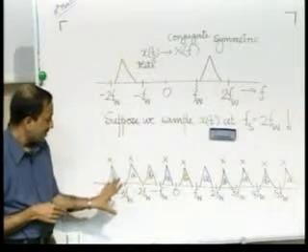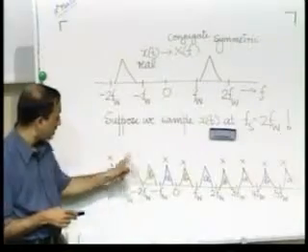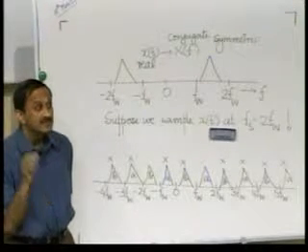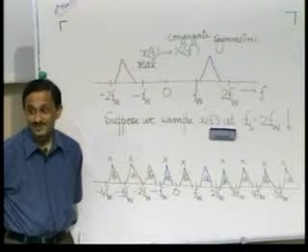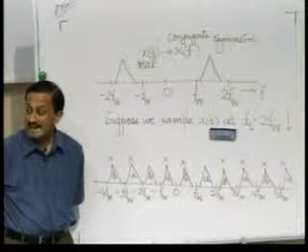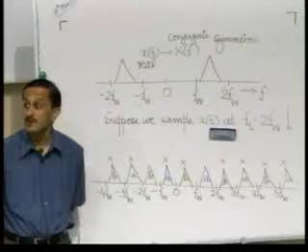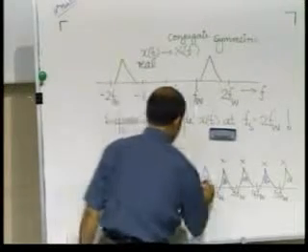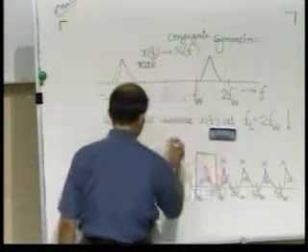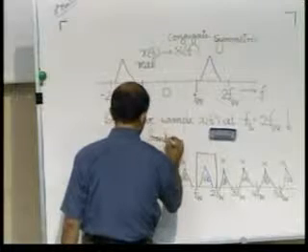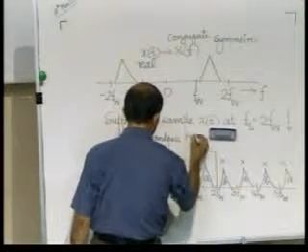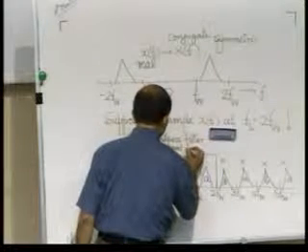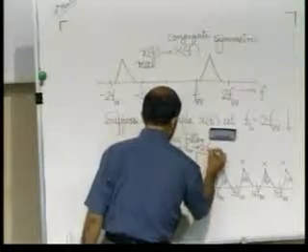Now you see, as a consequence of aliasing, we have created all the crossed spectra that I have shown. But none of those cross spectra interfere with the original spectrum. So, can we reconstruct the original spectrum? Certainly, but by what mechanism? By using a band pass filter instead of a low pass filter. So, suppose I put a band pass filter with a pass band from Fw to 2 Fw.